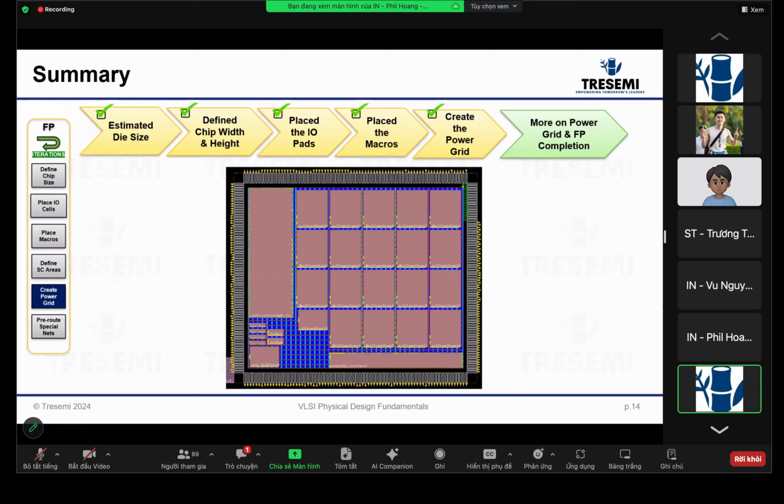So you build a grid according to your power specification, and then once you place all the cells, you route everything, that's when the final analysis will happen, with the EM and IR and so on. It'll be more accurate once you route and everything, with all the cells added for fixing setup timing, hold timing, and things like that. So the final will be done after the design has already met timing. Yeah, excellent. So in terms of power validation, exactly.